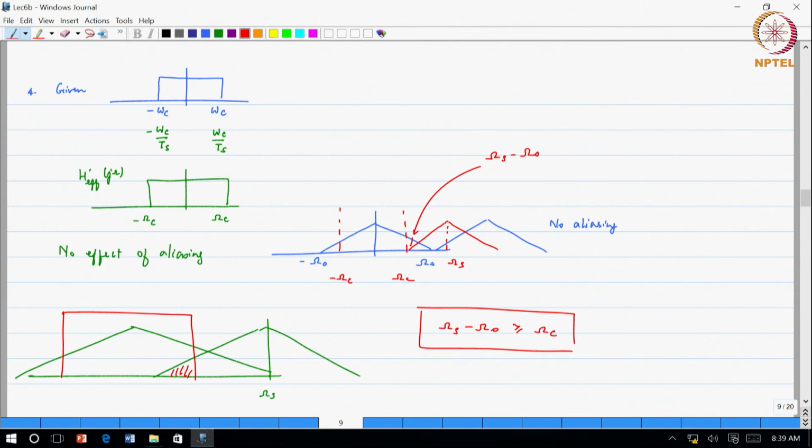So, as long as the input signal was band limited to omega naught, this framework would work, and that is one of the reasons why you would always have an anti-aliasing filter preceding your sampling process, because you always want to make sure that you are in control of when and how much aliasing will occur, because that is something that you always want to keep in check.